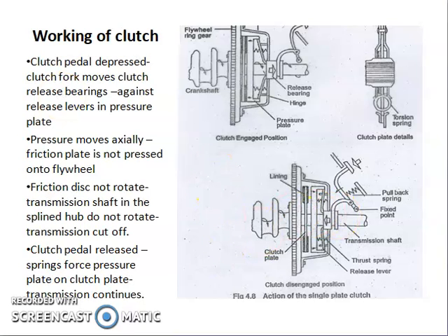So what happens when the clutch pedal is pressed? This shows the clutch in the disengaged position. In the disengaged position, you can see a small gap between the flywheel and the friction plate. When the clutch pedal is being pressed, it forces the release bearings inside.